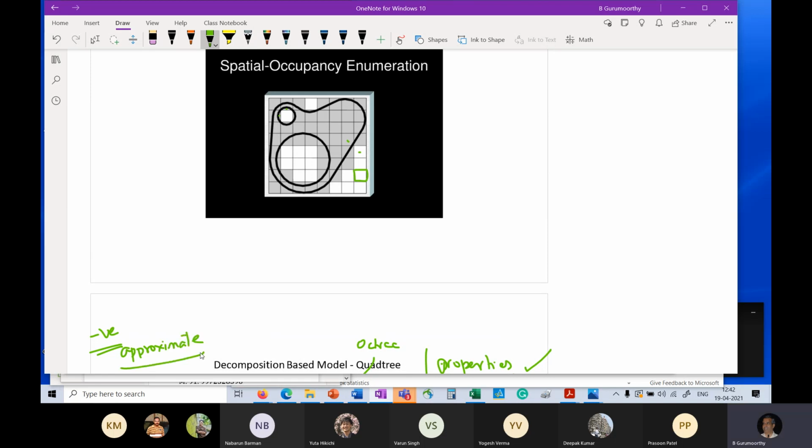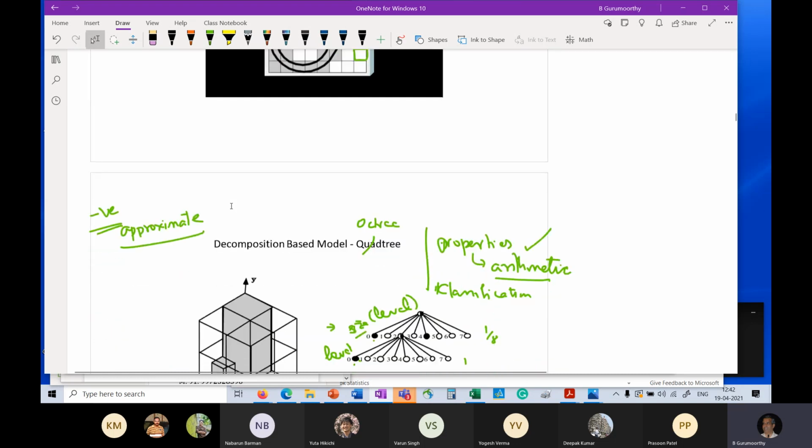It can never be exact, and it need not be even curved. As you can see here, this inclined edge will again cause you problems, because this much volume is not there in the part. This area is not in the part. But because I take the whole cell as occupied, I have to count that, and therefore I make a mistake in my computation of the area. Okay, and therefore that's a bad thing.